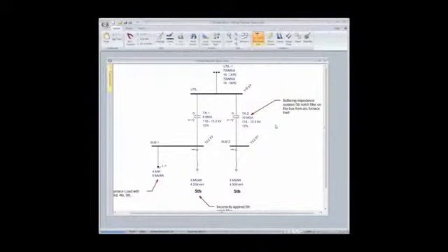Or we may want to apply power factor correction, and we want to avoid some type of resonant condition when we apply that power factor correction. So those are the two most key things we're going to be applying notch harmonic filtering for: avoidance and reduction in distortion. One of the most critical things, obviously, in a notch harmonic filter is its tuning.